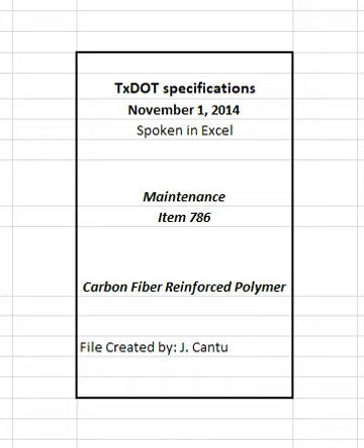Perform some or all direct pull-off tests on CFRP test samples prepared at locations of similar substrate near the CFRP installation area at the discretion of the engineer. Prepare the test samples using identical application procedures at the same time the project CFRP is installed. The required minimum pull-off stress is 200 psi, or failure in the concrete substrate, unless otherwise shown on the plans. Repair the damaged CFRP and concrete at test areas after testing is completed with thickened resin or putty.